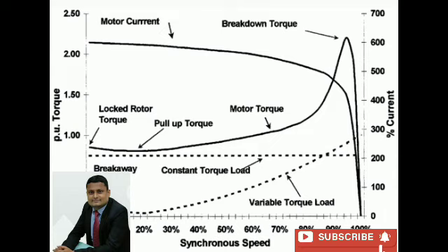Now the length of the rotor bar. Length of the rotor bar LB equals L plus allowance for skewing. These are the skewed rotor conductor bars, these are the end rings, and this is the skewed rotor conductor bars. Skewing is done normally for one slot pitch length, the stator slot pitch.